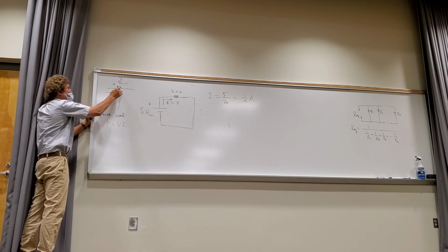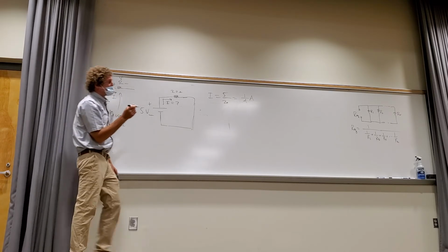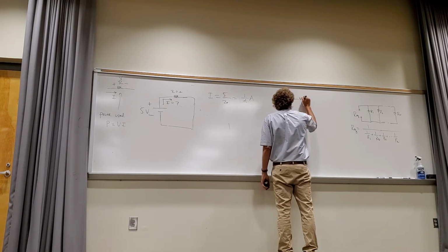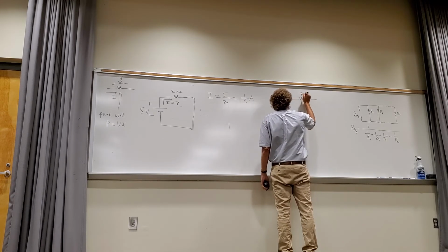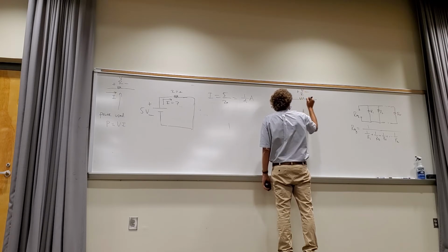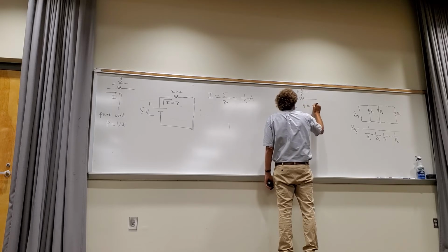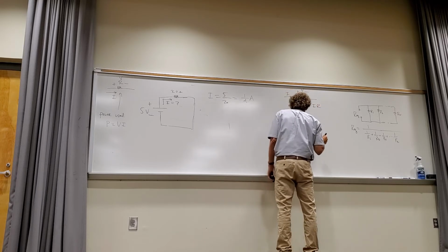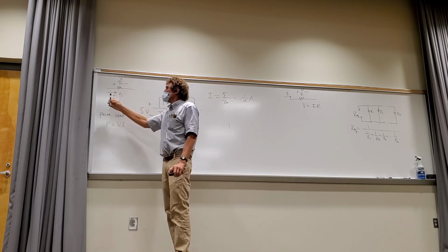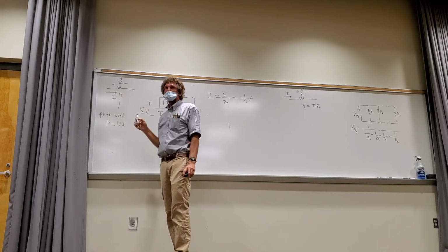You see how I put a plus and minus there? And here with Ohm's law, I don't think I did that, but in general, when you have a resistor R, and there's a current I through it, that gives rise to a plus to minus voltage V equal to I times R. You'll notice the position of the plus arrow here has to do with the current's entry point.